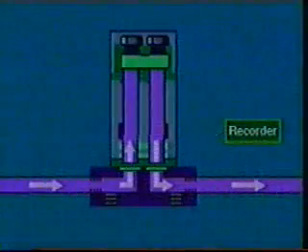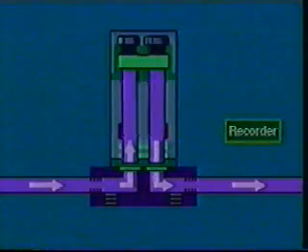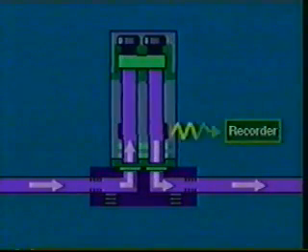The vibrating densitometer utilizes the vibration momentum principle. A sample of the liquid stream flows into the densitometer. The densitometer is vibrating at one of its natural frequencies, which is proportional to its mass per unit length. Because this vibration is also proportional to the density of the liquid in the densitometer, the density of the liquid can be calculated from the vibration frequency.